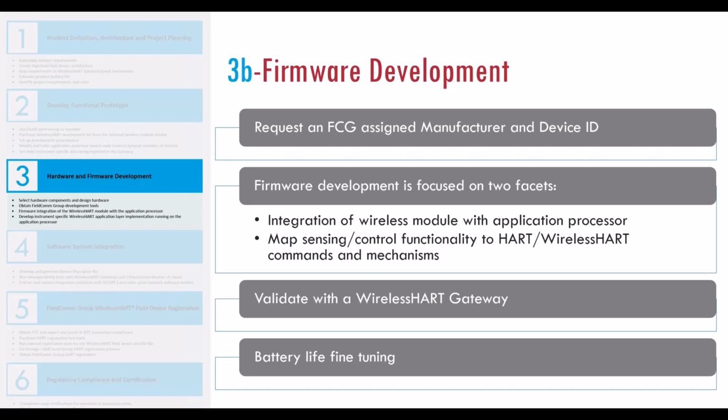So it is here that you would do some battery life fine-tuning and run a battery life optimizing schedule to where you ensure that you do not wake up the wireless module when it's not needed, because you do have the capability to wake up the WirelessHART wireless module at any time.